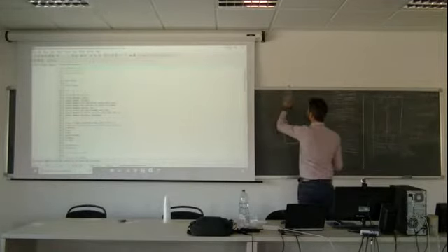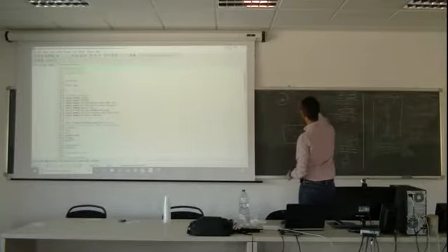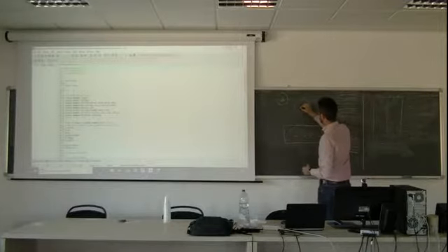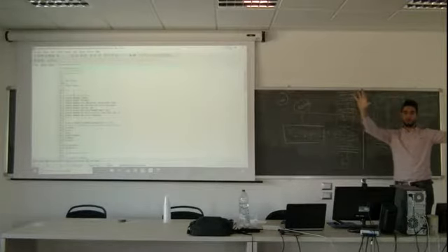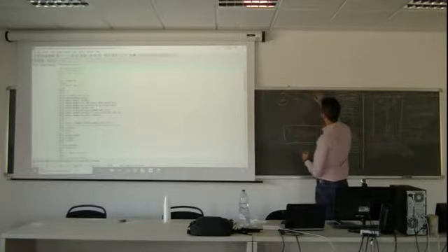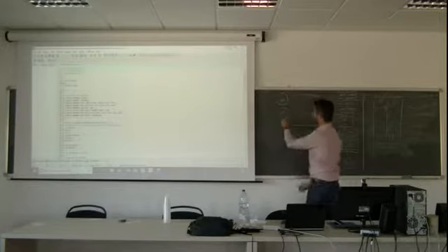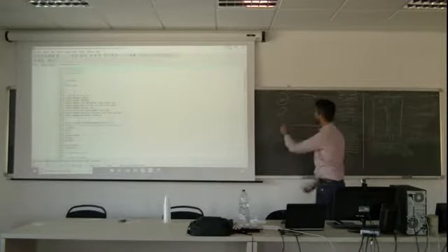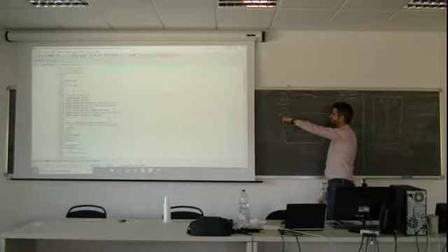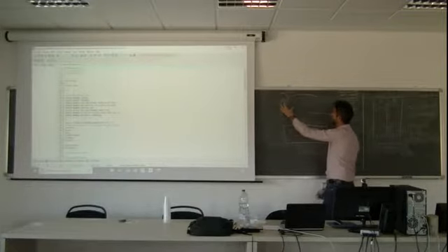We have a group which is the solution, a map of temperature, and a group which is the assumption. Right? We have solution and we have assumption. Map and map. Now, the new assumption was directly the solution. Right? I mean, we are in iteration number 0, first iteration. We assume one map. We calculate the solution. Is it the same? No. Okay, I need another assumption.